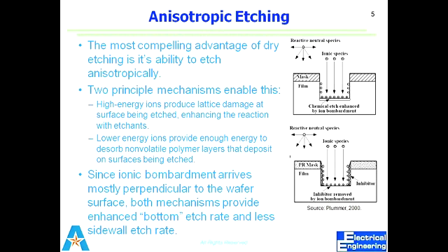Okay, so we stopped at this point last time due to that siren. We were talking about anisotropic etching. As I told you, in dry etching there are 2 mechanisms basically. One is ionic bombardment, and secondly, there is a chemical reaction. Those ions are very selective towards the surface, even if they are low energy ions, they can react with the surface and make it volatile and get away. So reactive ion etching is actually the combination of these 2. That's why we call it reactive ion. These are ions, and at the same time they are reactive to the surface.